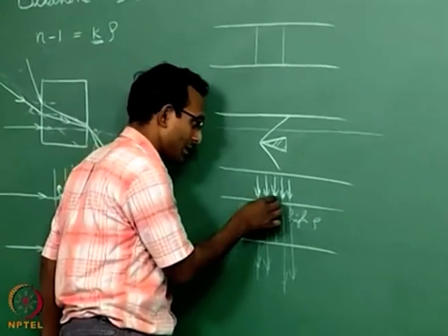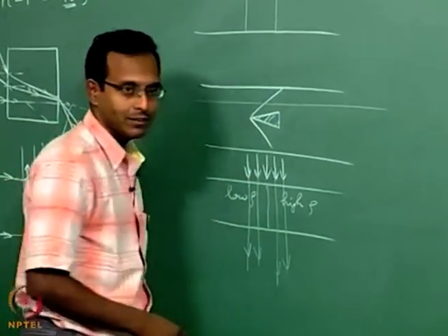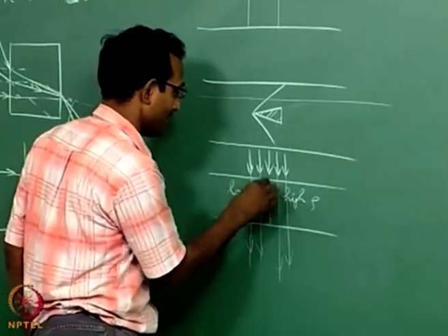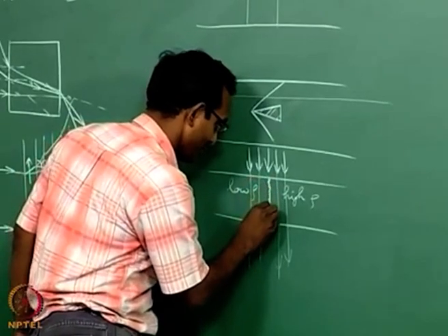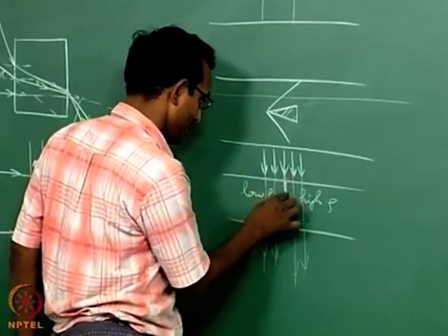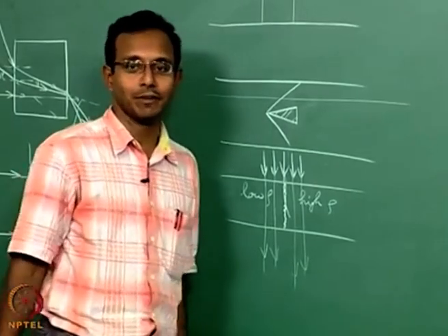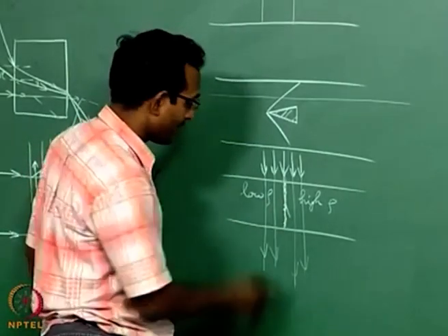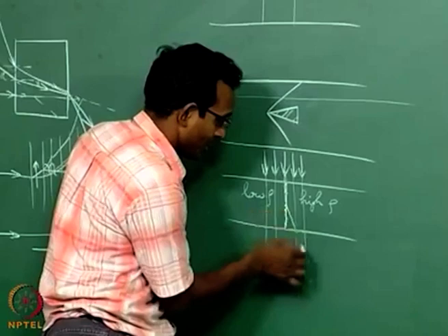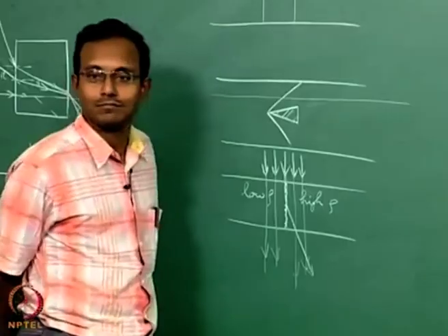But for this small region near the shock, that particular light ray that is coming in is seeing that there is denser medium this side, right. This is low density, this is high density, and this is my shock. I will make my shock this fuzzy line. This is my shock. What will happen? This light comes here and then it turns in, because it likes to turn into denser medium. So, it turns in. After it turned in, it is not seeing any other change, it is all constant density. So, it will just go straight, no more change, and then it is going to come out somewhere else.